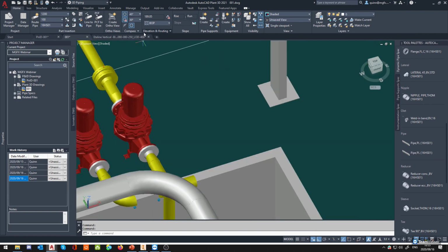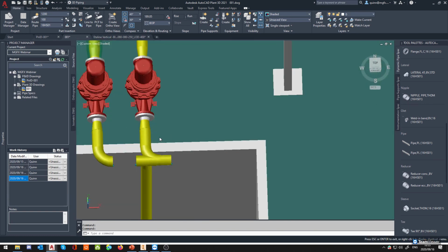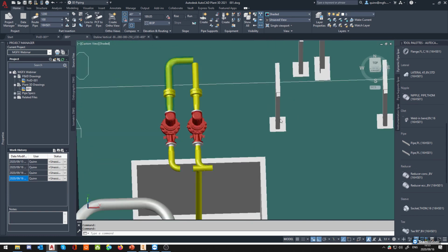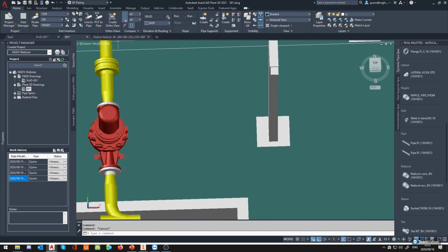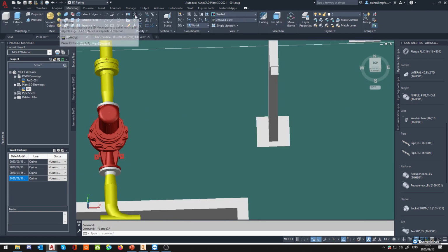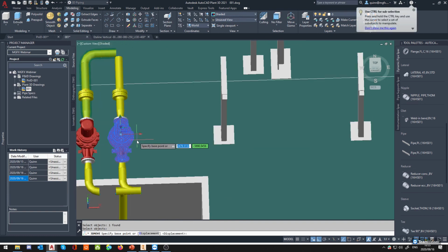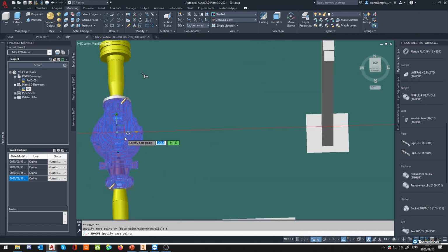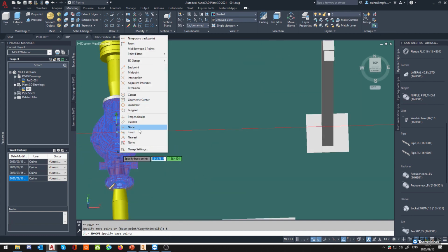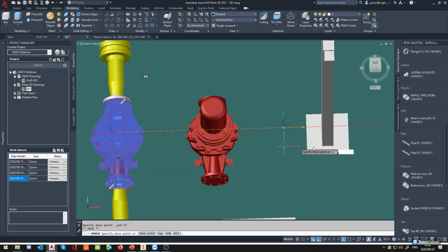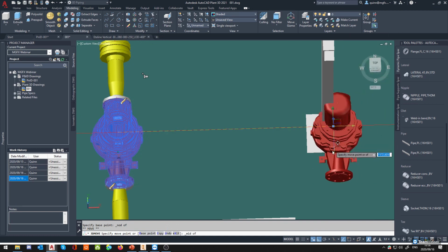Another thing over here that we can do is if you're trying to align something carefully, like let's say I'm trying to move my pump to the dead center of this item. You can go to modeling, select the 3D move, select the item, and accept. Now, this is where people don't realize that you can click one of the little arrows, go to base point, select node or something else that is in the center, and then move over to the center.